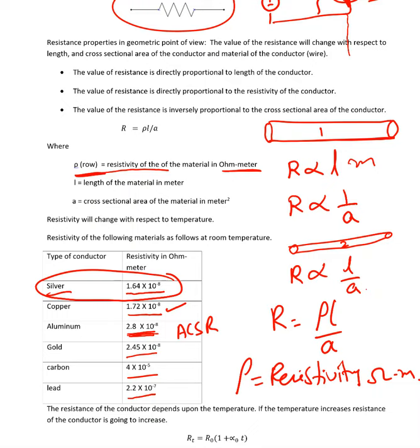But at the same time, if you hang a pure aluminum wire between two poles, by the end of the day it will reach the ground, because mechanical strength of the aluminum is low. So what they do, they keep an iron bar inside, and they wind aluminum wire around this iron bar, and call that an ACSR conductor. So the iron bar is going to give you mechanical strength for that conductor, and aluminum is a good conducting material.